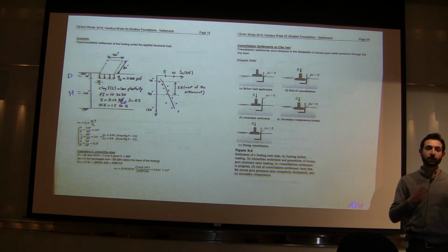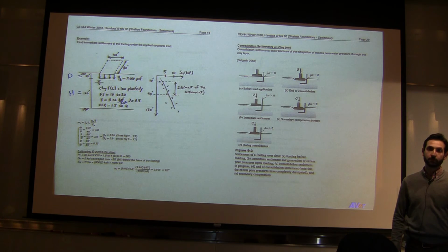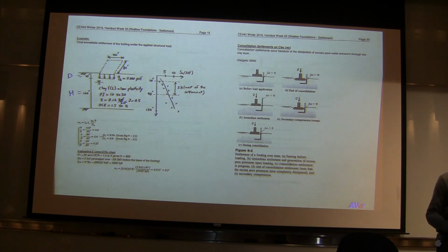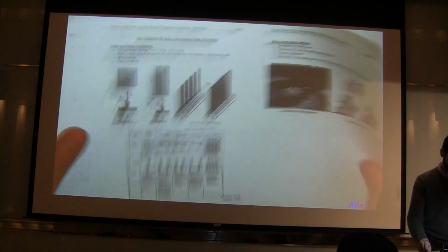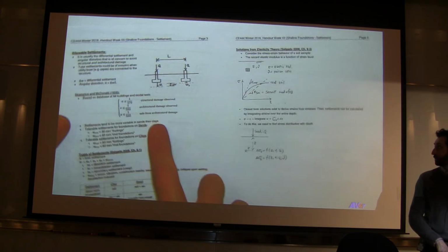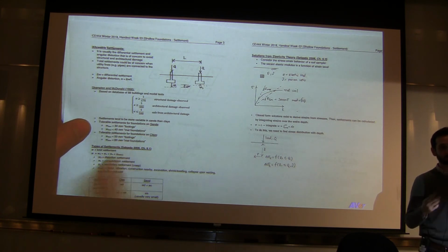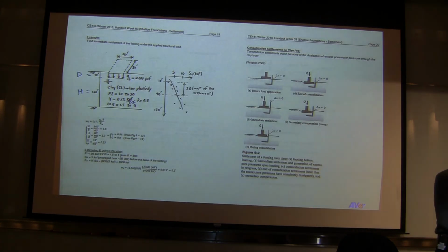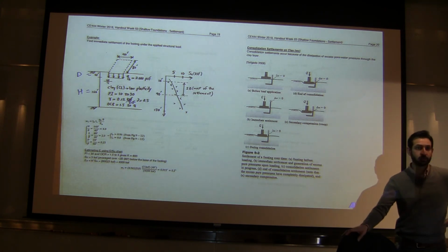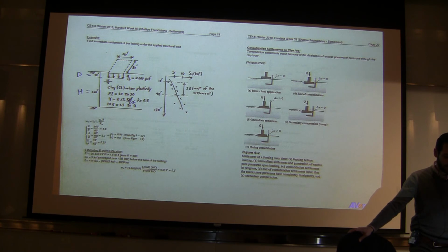So for shallow foundations, we designed for 2 factors, settlement and bearing capacity. All these stuff in this handout is settlement. So you want to minimize your settlement to be less than some tolerable values. And what are those tolerable values? They're all on page 3. So you either go with these tolerable values and minimize your settlements to be less than these limits, or the structural engineer tells you that, hey, we designed this bridge, we can tolerate ½ an inch. Design a foundation that can settle less than ½ an inch of settlement. So it's either given to you or you go with those typical ranges.